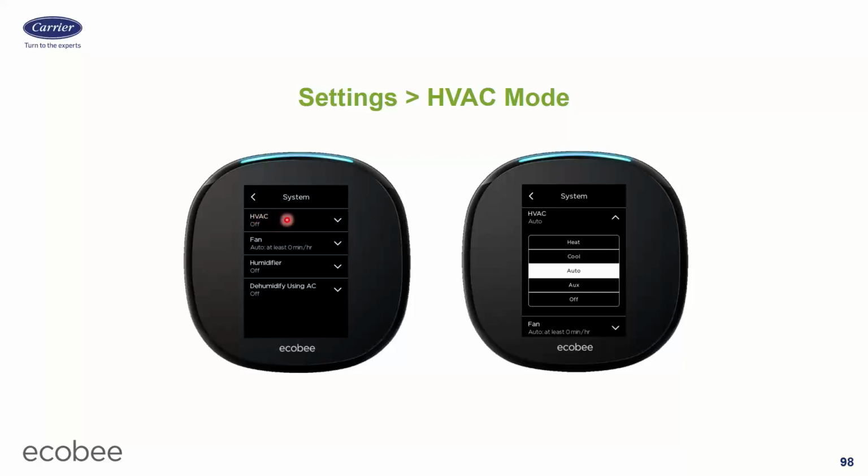So the first one, HVAC, that one's pretty self-explanatory. Heat, cool, auto, and off are your choices. There is also one for aux if you have an auxiliary heater with a heat pump. If they put it in aux, it is not going to run the compressor heat pump. And aux, we already said, was the least efficient thing to do. So you don't want to run it in aux. You want to leave it in auto and let it make its own choice.